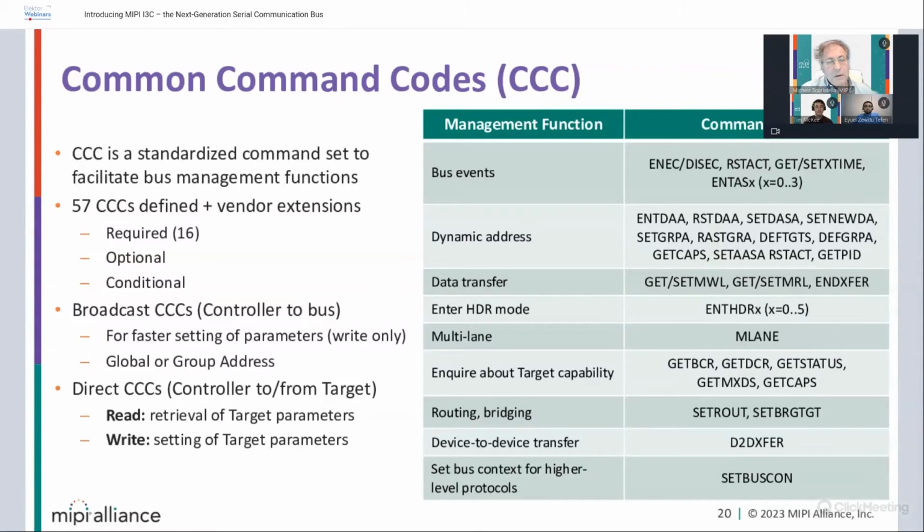We have a slide after to explain a little more. But basically, in I3C, you are not hardwired with the manufacturer address, like it is in I2C. In I2C, you buy a device, and the device has a fixed address, or maybe has one or two pins to manage it, but it's basically hardwired. Here, it's dynamically assigned by the controller.